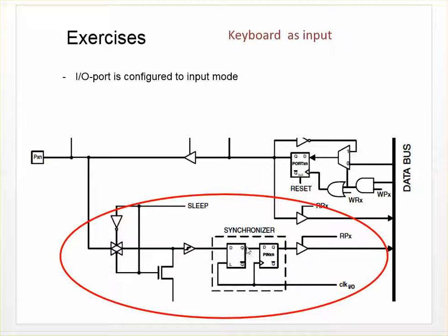If you simplify, you could think that the signal goes from this input pin through this sleep circuit, through these latches to here, and here's that 3-state buffer or electronic switch which lets the input signal to the data bus for a very short period when the CPU is reading it. At other times this 3-state buffer is disabled and does not let any signal go through.